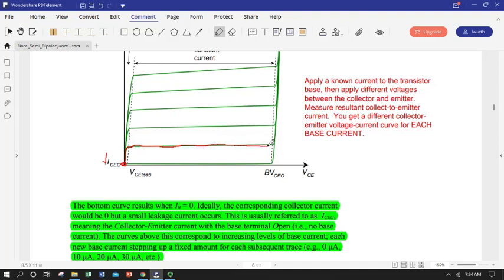It's a flat line, kind of like an ideal current source, just doesn't really care until we again get to the breakdown voltage, which we're not going to get anywhere near because we're going to use a proper current limiting resistor. This is bad. We don't want to go beyond there. But we've got this beautiful region in here of constant current. But we also know we're not going to get any more current no matter how much we turn up the collector to emitter voltage. And in this way, a bipolar junction transistor is very different from a resistor.